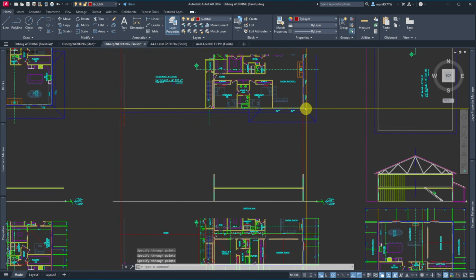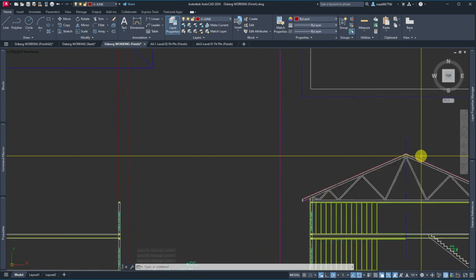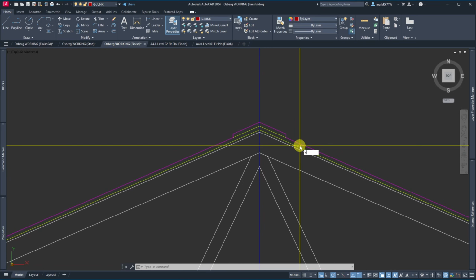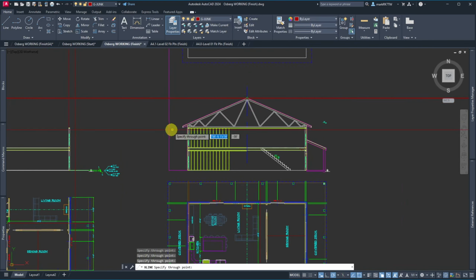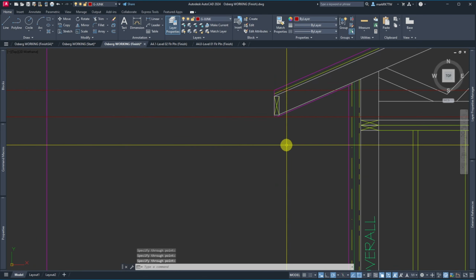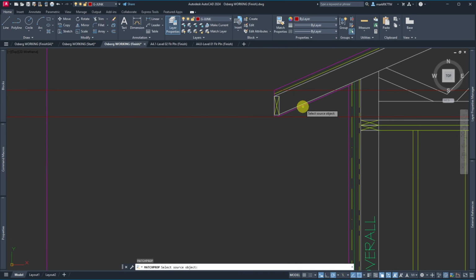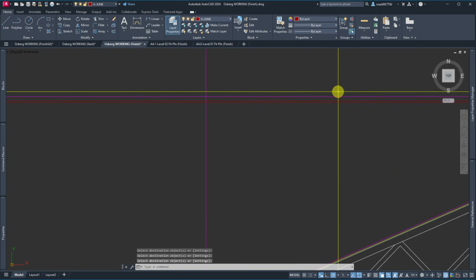So now that I have those 2 termination points, I can take and put in some X lines here. And put them in horizontally, H, there, here, there, and there. And now I want to match the bottom one, so I've got something to play with over there, and I'll need the top one anyway.